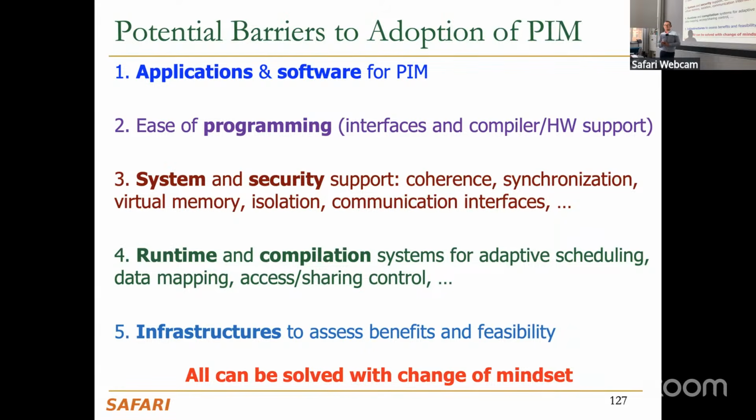It's good to examine both in research, but for adoption purposes, it may be good to go little by little. RowClone is easier to adopt, and by violating the timing parameters, you can get mostly reliable RowClone. You can design a compiler for it. You can even ship a product with it. I don't know if you'll make profit, but it's possible to do that with RowClone, for example, right? It's a relatively simple thing. Existing DRAM chips can do it, but there's a lot of adoption issues at the higher level.